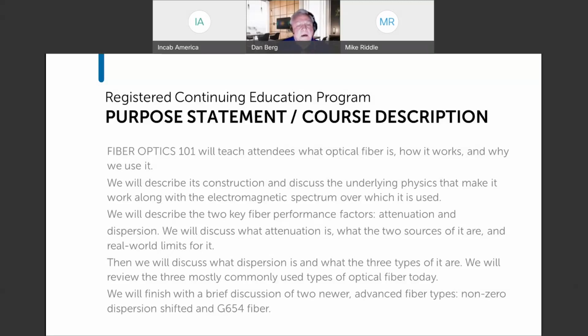A little bit of history. Optical fiber communications more or less started in 1966 when Charles Kao and George Hockham at Standard Telephone demonstrated that you could transmit information from a laser through an optical fiber and get that data on the other end. Unfortunately, the fiber was so poor they could only do a few meters. Kao said that if you could continue to advance and make the optical fiber clear enough to reach less than 20 dB per kilometer, it would be a viable transmission medium. In 1970, a group of 3 scientists at Corning Glassworks made the first fiber with less than 20 dB per kilometer, and it's been going gangbusters ever since.